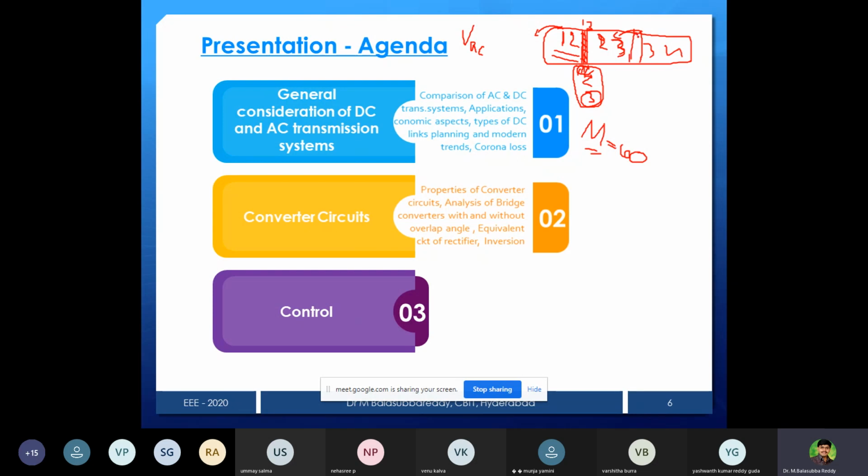Again, after the 2, 3 instant, let it be after 60 degrees. This will happen only within 60 degrees of time. Earlier in the power electronics case, for a total of 60 degrees 1, 2 will conduct, the next 60 degrees 2, 3 will conduct, and then 3, 4 like that. But within 60 degrees of time, two sub-intervals will come into the picture. One interval is 2 valve conduction, 1 and 2. Another interval is 3 valve conduction, 1, 2, 3.